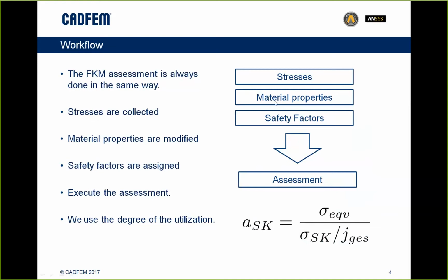With material properties, I mean I have my yield, I have my ultimate. And usually we have the yield and the ultimate for our sample. So I have a small sample, and we put our small sample on the testing rig. And what we then get is a value that is true for the small sample. What we have in reality is that our sample will be much closer to perfect than our real part.